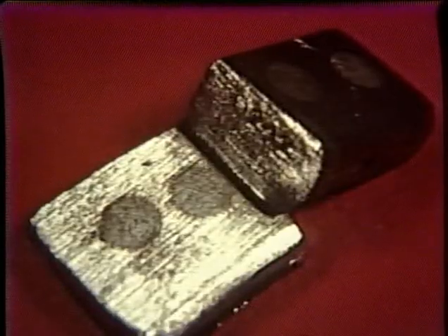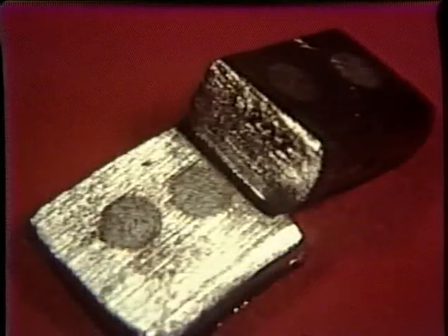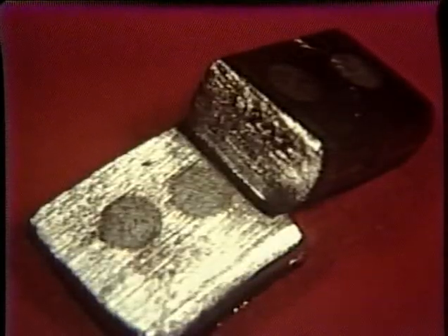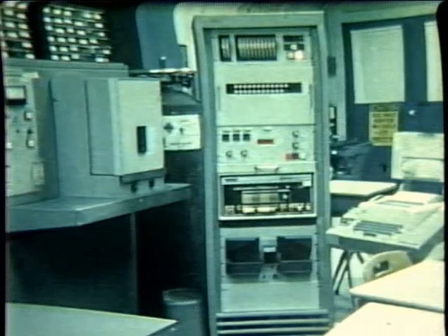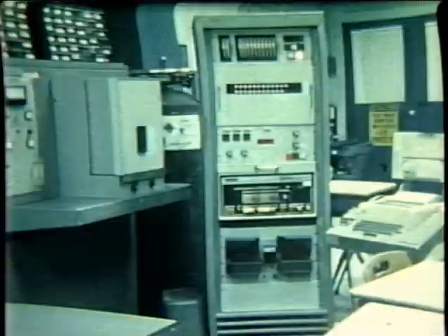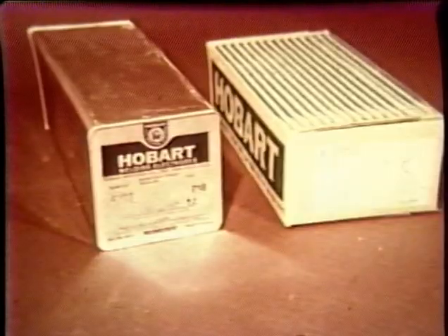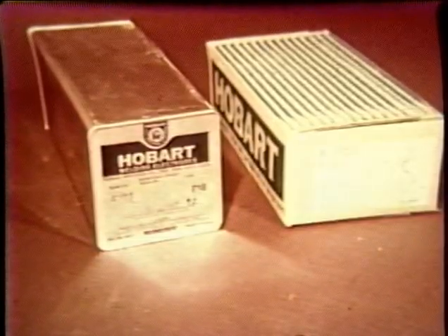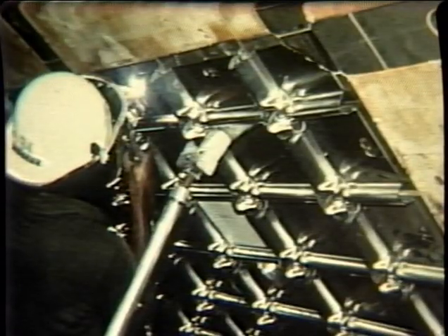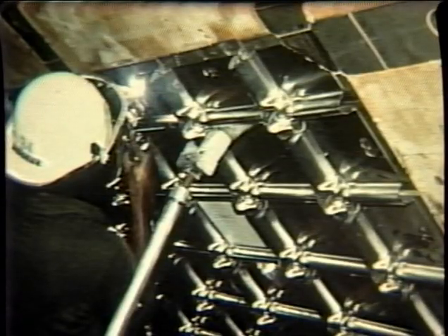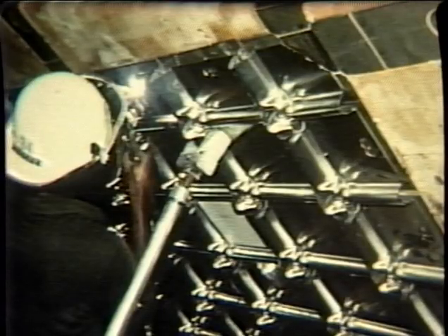Destructive testing also includes chemical tests. Welded joints may be cut to remove sections for analysis of alloying elements. Specialized equipment in laboratory conditions, such as spectrographic analysis, can be used to evaluate chemical composition. This is important to filler metal manufacturers, where electrodes must be produced to meet minimum alloy requirements. Chemical composition is important for weldments requiring corrosion resistance. Chromium and nickel content, as well as carbide formations, are analyzed to determine the metal's ability to perform in service.